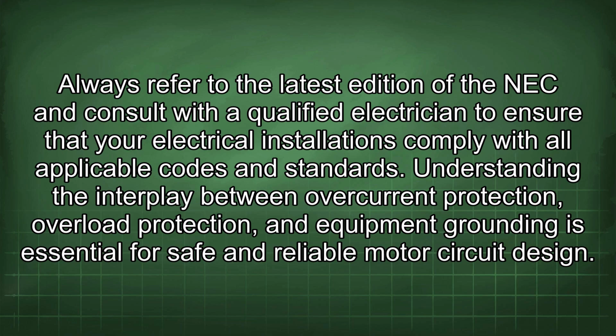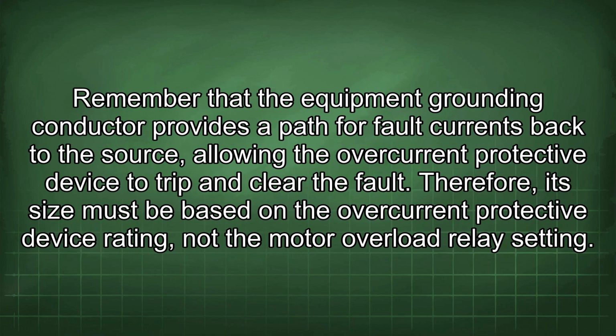Understanding the interplay between overcurrent protection, overload protection, and equipment grounding is essential for safe and reliable motor circuit design. Remember that the equipment grounding conductor provides a path for fault currents back to the source, allowing the overcurrent protective device to trip and clear the fault. Therefore, its size must be based on the overcurrent protective device rating, not the motor overload relay setting.